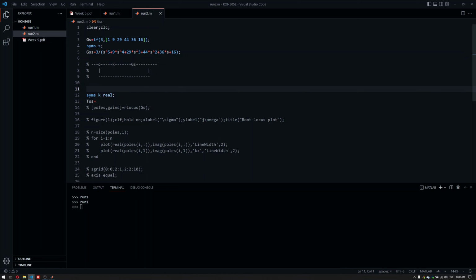So before this, we had G(s), or the open loop poles, which are basically the poles of the system under control, or the plant. And then we have a static gain. We place it in a unit feedback where we have a minus sign here. So we're basically measuring the output. We have a certain input in our mind. We take the difference. We take k times that difference, or the error, and apply it to the system so that we can adjust the output. We are trying to regulate the output.